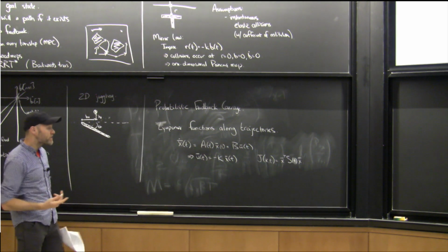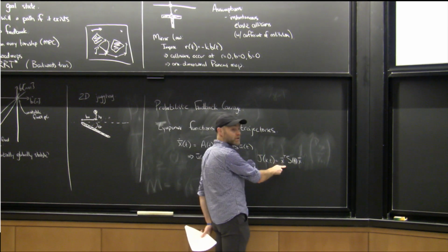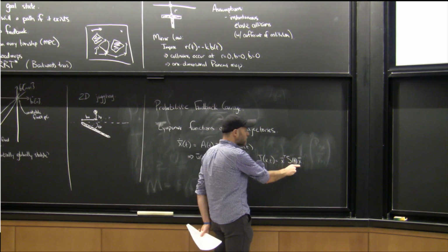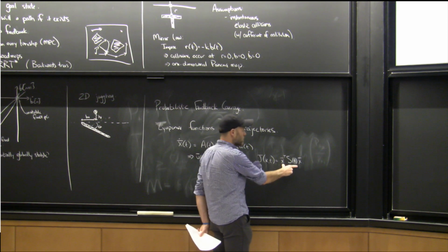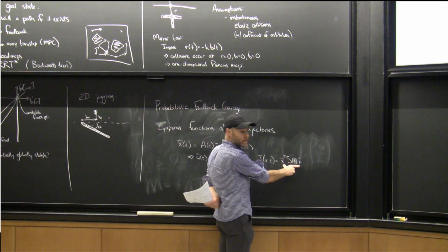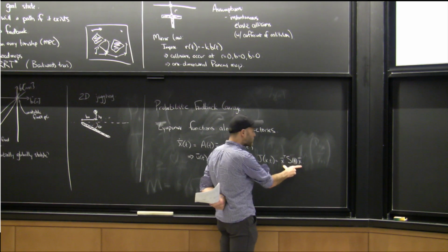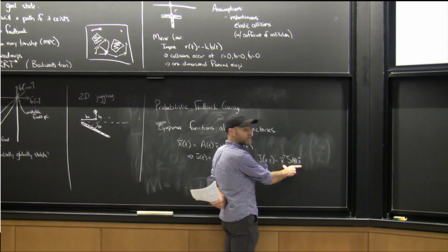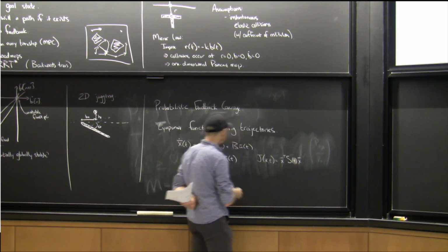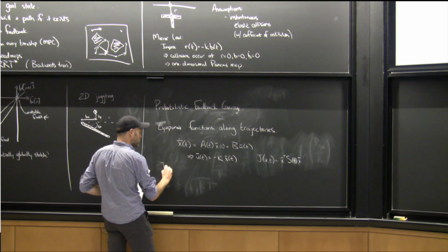Okay, so for the linear system, we know that this is going to go downhill. This is going to be strictly less than or equal to 0. And the original question that we wanted to ask was, does this always also go downhill and prove stability of the nonlinear system? But the operation I need for this feedback motion planning to work is a little different than absolute stability, right? Now, the details are, I have a trajectory,